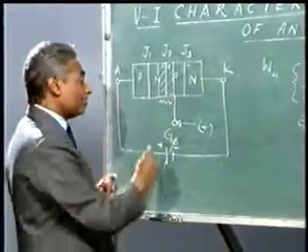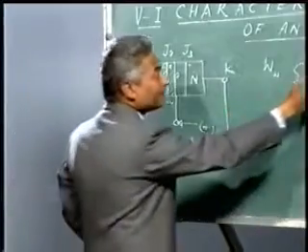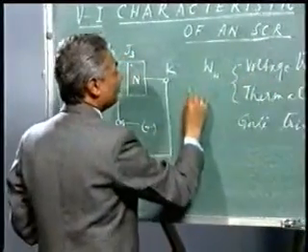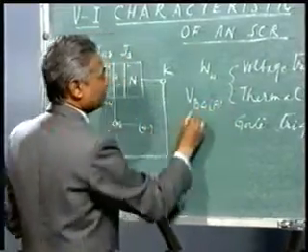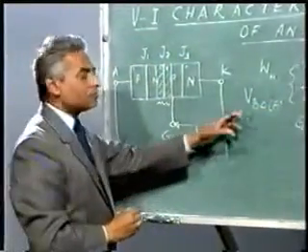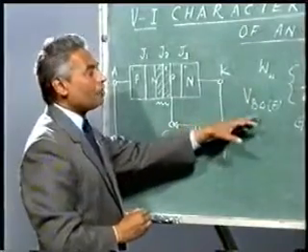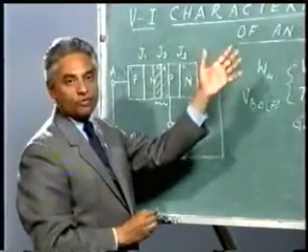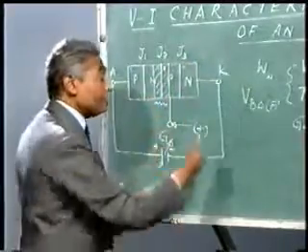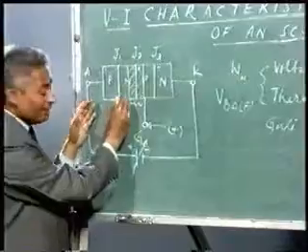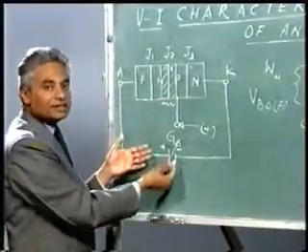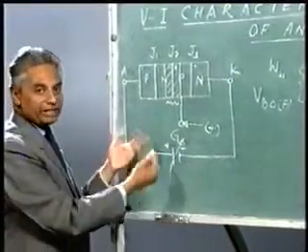The voltage at which this started conducting here was known as VBO. We call it VBOF, which is breakover voltage, of course, forward. So the forward breakover voltage may be 600 volts, 700 volts or 800 volts, but without going up to that, with the help of gate triggering, we can trigger the device even at a lower voltage, say supply voltage of 220 volts or even lesser than that.